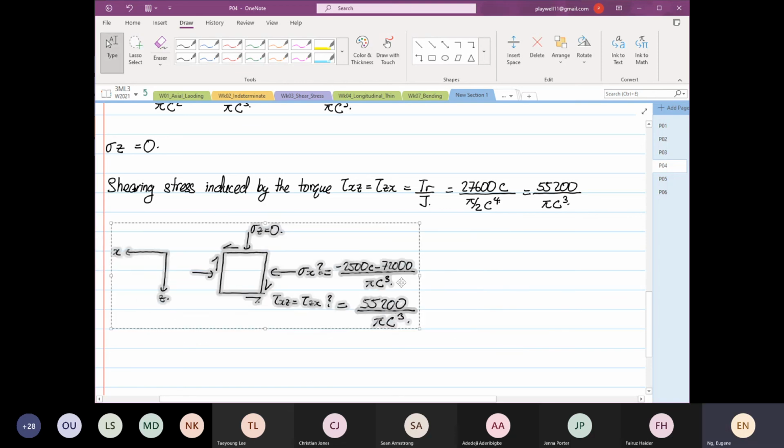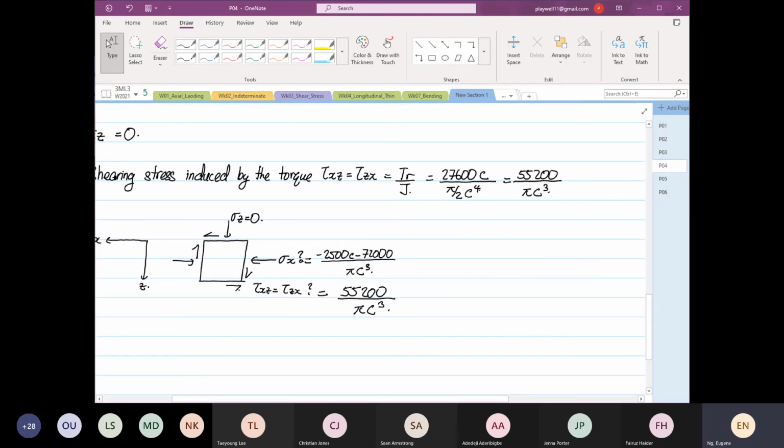Now it is basically solving Mohr's circle and incorporating Tresca's criterion to select the radius of the shaft. So we have to find stress A and stress B, and also tau max.